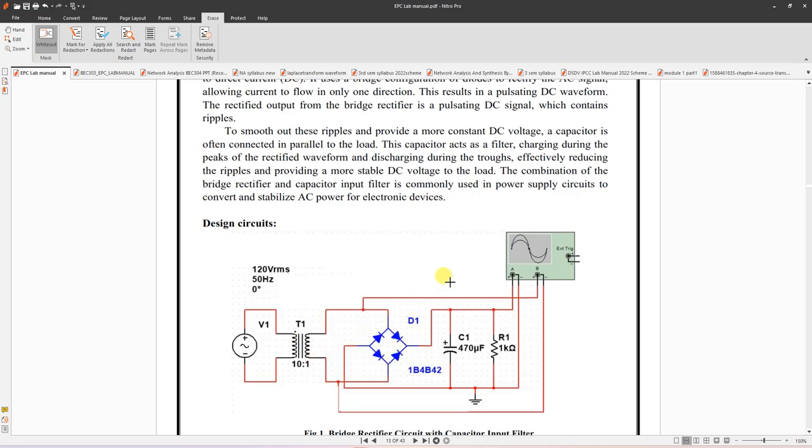And in the negative half cycle, this point B is positive and this is negative. This is connected to the positive here. This is forward biased and this is also forward biased. Now these two diodes are reverse biased. So these act as a short circuit, and these two act as an open circuit. Now current flows from plus, goes here, goes to the load, and again comes here. So this is a full wave rectifier where both positive and negative cycles are rectified.